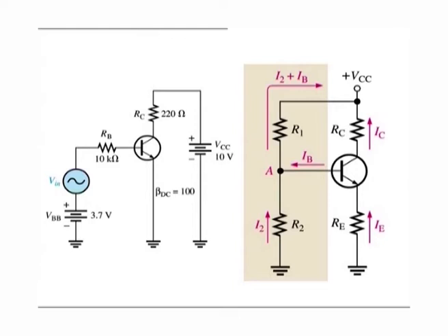To simplify the schematic, the battery symbol is omitted and replaced by a line termination circle with the voltage indicator VCC as shown. The DC bias voltage at the base of the transistor can be developed by a resistive voltage divider that consists of R1 and R2.